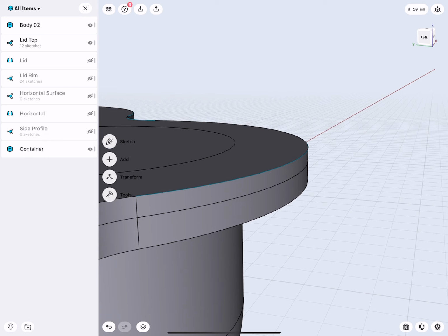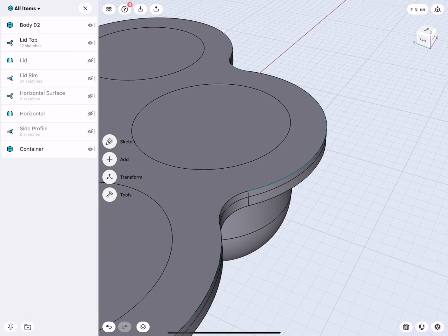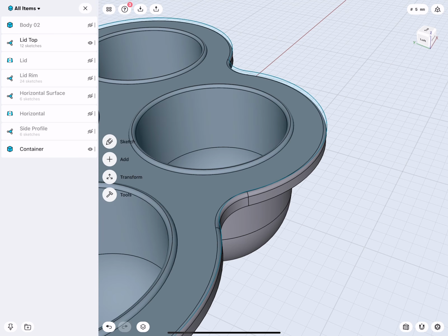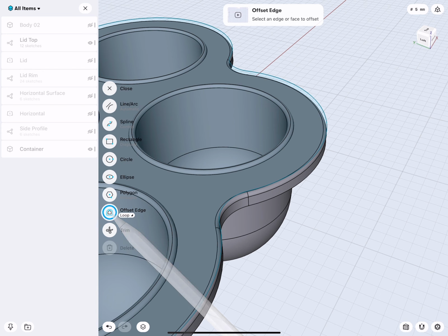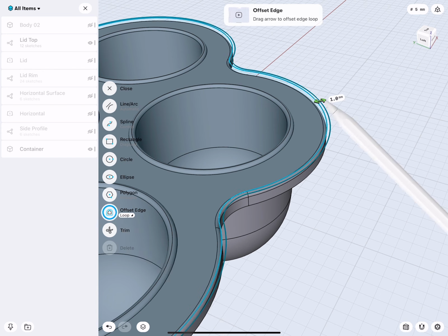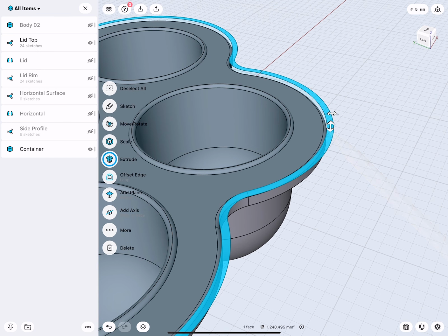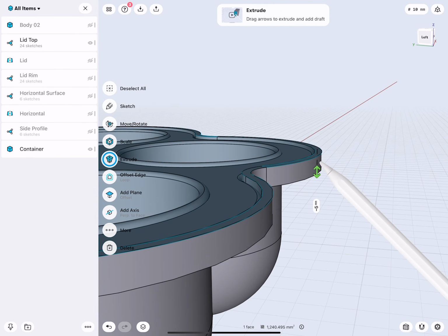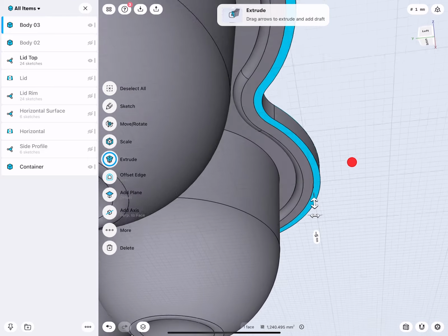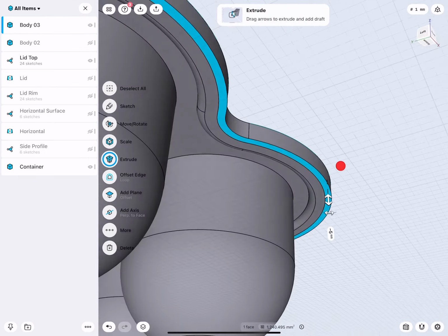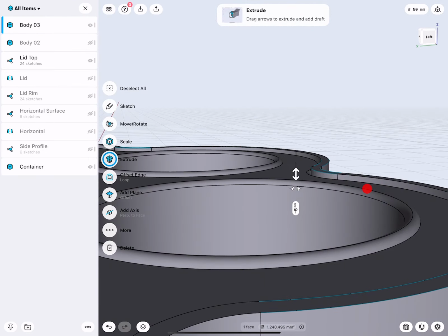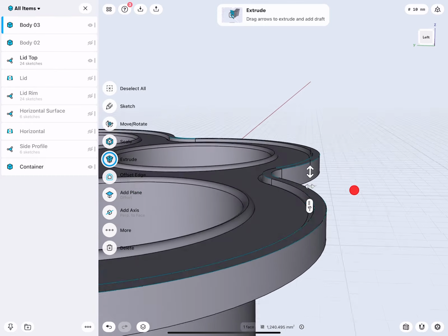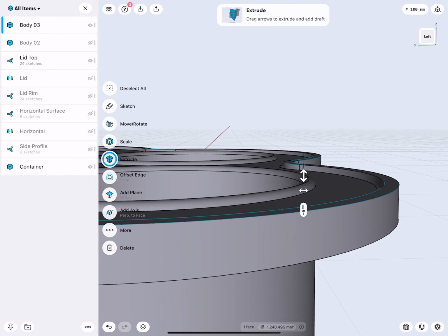Along the sides, we would like the lid to go down too. So how do we do this? Also here, very easy. 2 millimeters material thickness. Okay, so I need, in addition to the sketch, I do another offset by 2 millimeters. Select this, new profile, and then I can go down. But how much? 5, is this okay? This looks good. Okay, very good.